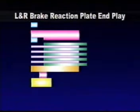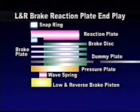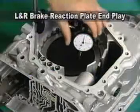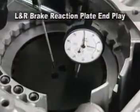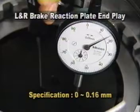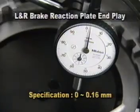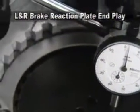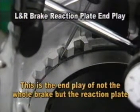Assemble the wave spring, brake plate and disc, reaction plate and snap ring starting from low and reverse brake, and change the brake plate that is located at the lowest part with special tool dummy plate. Install the dial gauge and measure the end play by moving the dummy plate up and down. If the measured value exceeds the specification, change the upper ring with one of the 4 different rings in thickness. To emphasize again, this is the end play of not the whole brake, but the reaction plate.